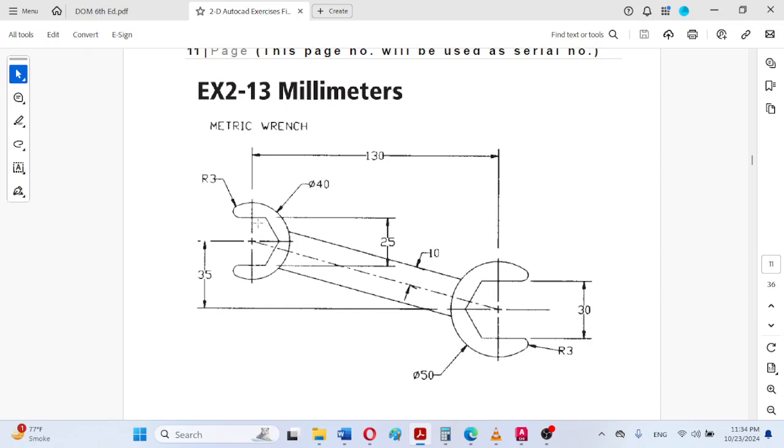The type of polygon that we will be using is circumscribed about the circle, because the specifying circle will be made inside this polygon, or this polygon will be circumscribed about that circle, and the sides of this hexagon will be externally tangent to that specifying circle at their midpoints.